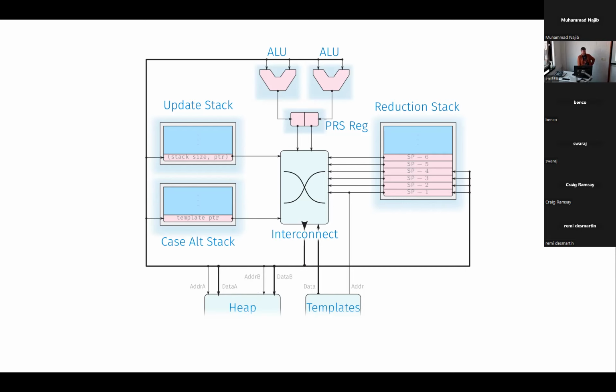So the downside of having this really simple design that's not pipelined is, well, it's all stack-based. Everything we do is going to be directed by what was left at the top of the stack by the previous cycle. So I'm saying it's not pipelined. We can get good performance without it, but really it's because it's hard to pipeline, right? There's this data dependency between every single adjacent cycle. But there's only a few different operations we have to support here.